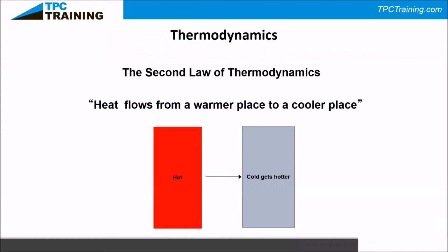system. It's important to understand that you need a certain amount of BTUs of heat energy pulled out of a space to get us down to a comfortable temperature. Comfort cooling usually refers to a range of around 70 degrees Fahrenheit. The majority of us feel comfortable at 70 degrees. But again, we need to make sure we're removing enough humidity, because if we're at 70 degrees and we don't take enough humidity out, we're still going to feel uncomfortable.